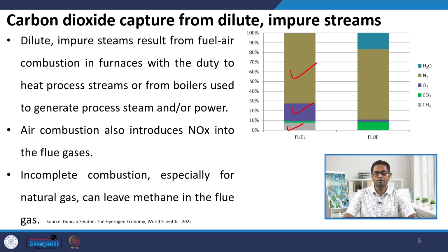After the gas is burned outside the reactor, which is the sole aim of providing heat to the reactor, the output nitrogen remains as such. Some of it of course gets converted to NOx emission, but that's very less. Majority of the nitrogen escapes as nitrogen, and this is what you can see in the flue gas as well. Majority of the flue gas composition is made of the nitrogen content.